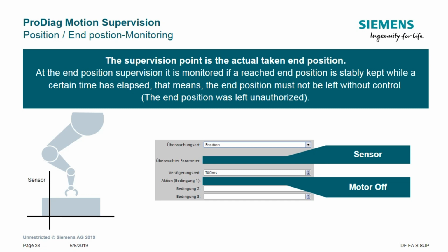I guess interlock is clear, releasing an interlock. So if I do have here a function block, and I do have one parameter here, which is in that case called release, so releasing the function here. I have one pre-requirement here, which is the global release, which has to be active in order that the precondition for this release is fulfilled. Okay.